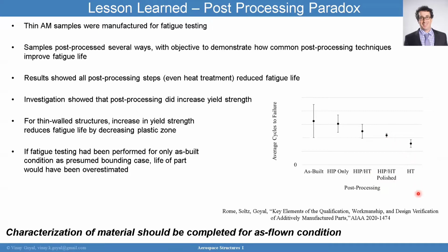But it didn't necessarily have a big effect, in none of those cases, except do we actually get better performance by doing the post-processing? I guess if you did, because you do the HIP first, that makes it lower. You do the heat treatment, that makes it lower, and then you polish it, and it may be lower. It may be about the same. It's hard to say there. But you want to understand that too. It's like, okay, polishing doesn't look like it matters. It just gives you more consistent results.